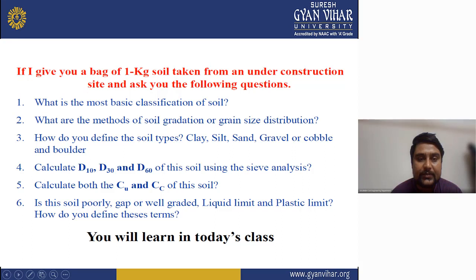Soil particle classification is given here, and these are the organizations which gave methods for soil classification. Now we will see the grain size distribution, also known as GSD, and its significance: to know the relative proportion of different grain sizes. It is an important factor influencing the geotechnical character of coarse-grained soil, but not important in fine-grained soil.